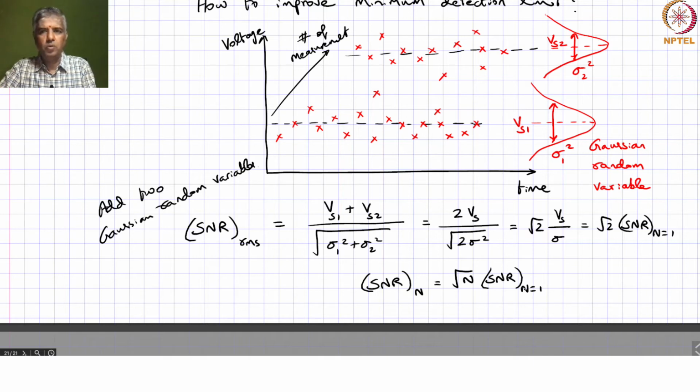We were just going through an overview of the course, and at that time we were talking about distributed fiber sensors. And in distributed fiber sensors, the amount of backscattered light is typically very low, so it's corrupted by noise at the optical receiver, and because of that the signal to noise ratio is typically quite poor.